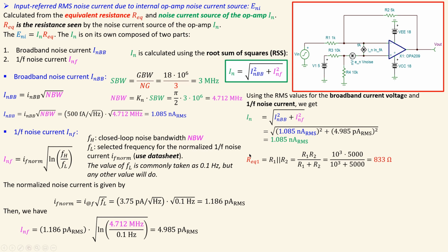Of course now we have a different situation, because we need to calculate the equivalent resistance for this current noise source, and here we see actually two branches seen by this noise current. That will be R1 and R2 in parallel, because this is a short which is disabled, and this is also a disabled part. But it also sees, since this is disabled, which is then short, and this is also disabled because we use superposition, R3 and R4 also in parallel.